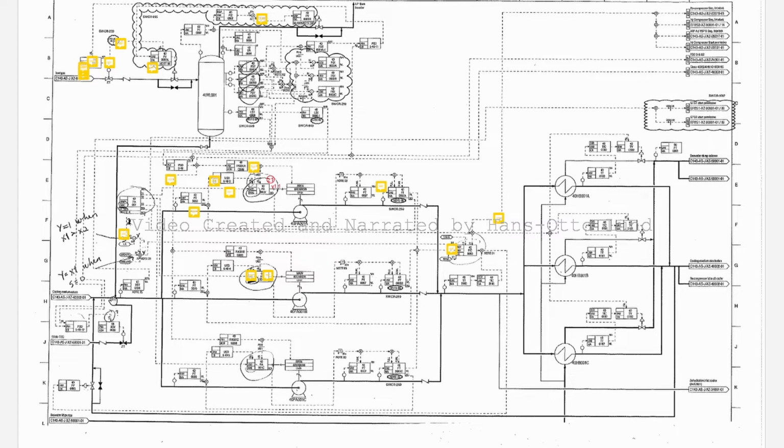So liquid can go freely both ways from this tank to supply the line here, or if there is too much pressure here, some of the liquid will be pushed back up into the tank. And you can adjust the pressure of the nitrogen atmosphere to set a suitable pressure for the line here, the suction side of the pump.